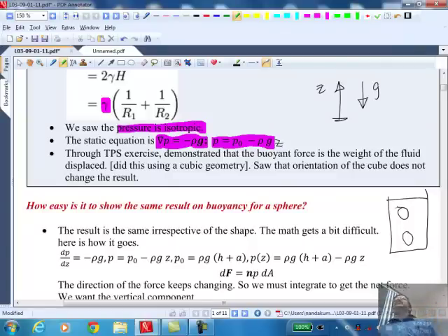It depends on the magnitude of the force I gave. But when I give it a force, is there any other force that is stopping it from moving? These are the thought experiments that you can continuously do while you're taking a bus, while you're driving, so the fluid mechanics becomes second nature to you. So if the particle is moving, there is a relative velocity between the particle and the fluid. And that means there is a shear, there is friction. That's what is going to bring it down to a stagnant position again.